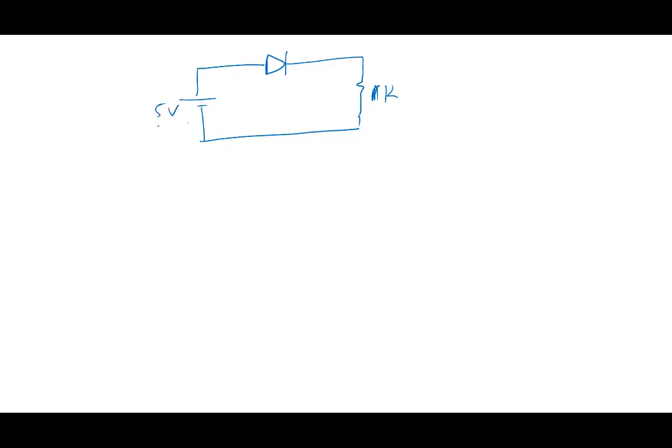We have a circuit like this, and even for a single diode simple circuit like this, the analysis is becoming complex. Analysis is getting complex because we have to do it in multiple steps: assume a value, substitute it, get the current, recalculate VD, substitute again, and repeat.